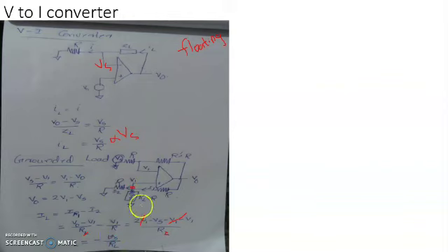We have taken R, RL, R1, R2, R prime all equal to say R. So you can put this RL also. So IL equal to minus Vs divided by R. So for this circuit also, load current is proportional to the voltage that needed to be converted into equivalent current. So this can also function as a voltage to current converter. However, in this case, comparing with the earlier one, the load is not floating, it is grounded. So this kind of a voltage to current converter is referred to as voltage to current converter with grounded load.